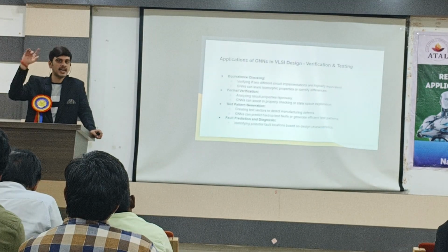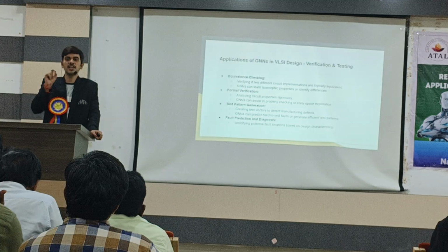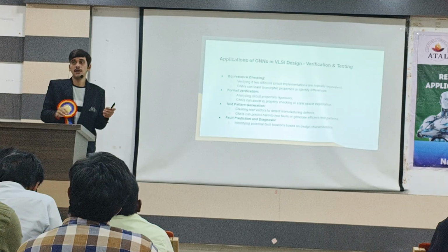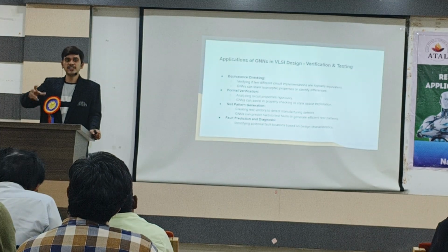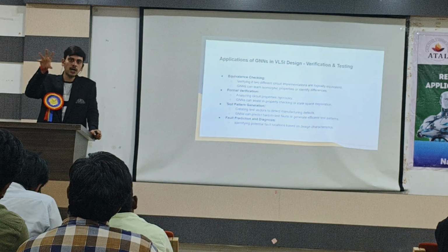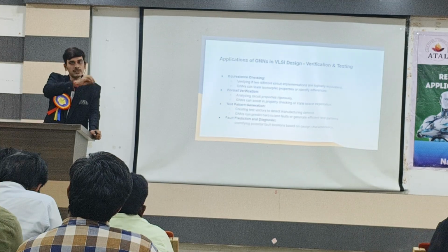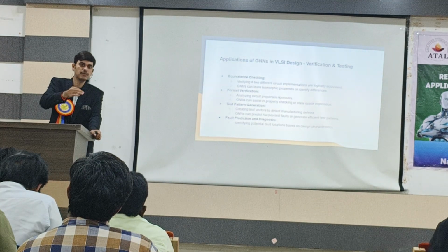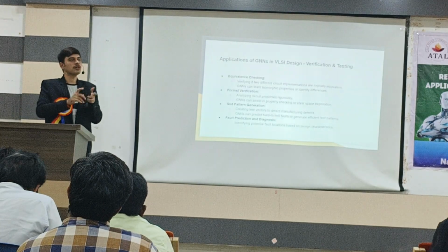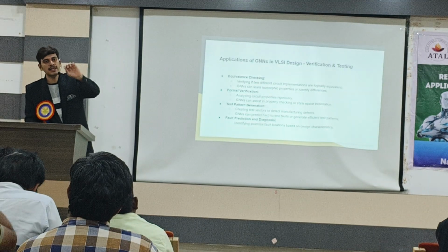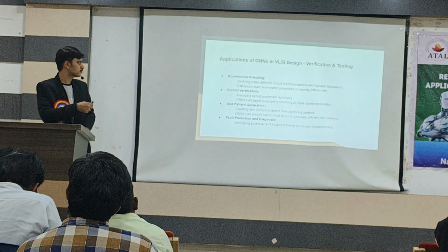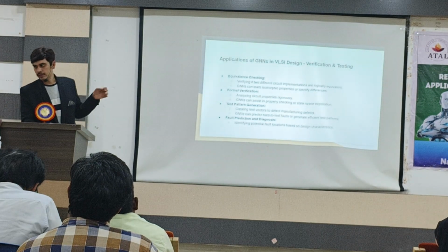The timing owner won't change the functionality, but the RTL owner, if they want to add some specific feature during the course of the project, because initially they have specifications for particular features. For example, they want some feature to be added in the mobile SoC. They will release some functional ECO, so that the application logic will be in the functional ECO. So we have to check the functionality at every stage of ECO. It should match with the previous revision, so that it is the same. That's called equivalence checking. For example, instead of 2 inverters it will be 1 inverter, and the functionality will vary. So we check that with Formality. Formal verification is the key equivalence check.